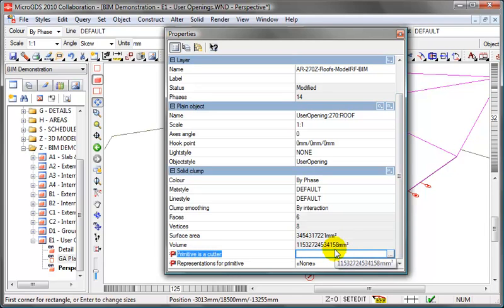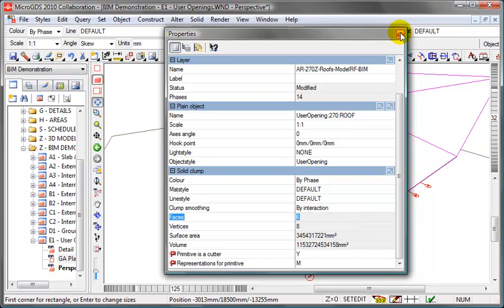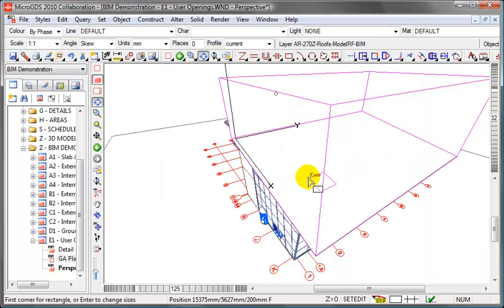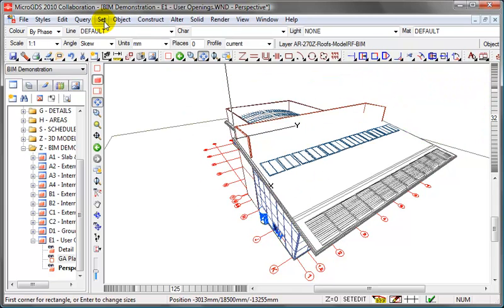Any value will do. MicroGDS doesn't care what you put in here, so we'll just put a Y to say yes. And we need to set a representation of M so that the cutter itself is visible when the object is the only selected object. And again, snap somewhere else in the box to set that value, and we can close it. Set the axes centre again.